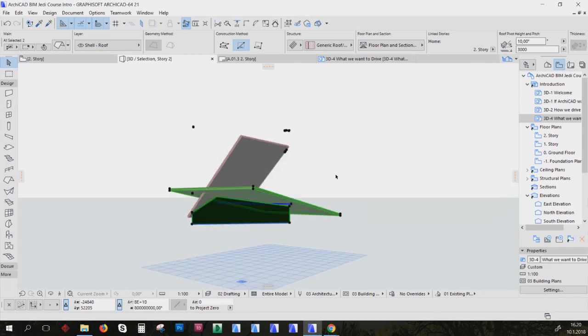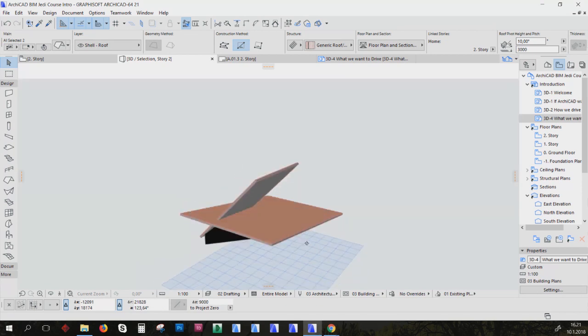So if you've got overlaying roofs and you want to crop the wall to only one of them, you select the roof that's applicable and the walls and just push Control 0, so it crops to those two amongst the things you've got selected.